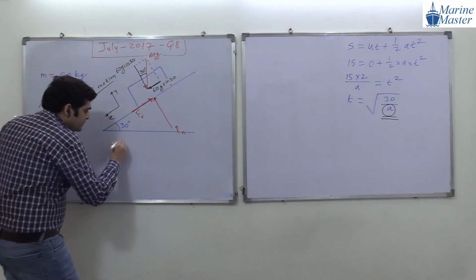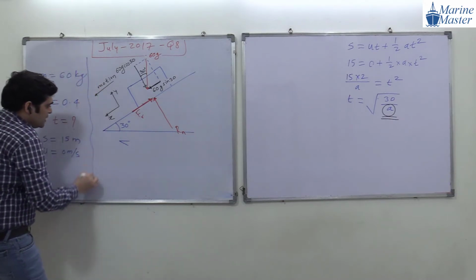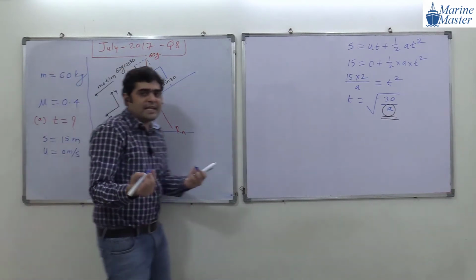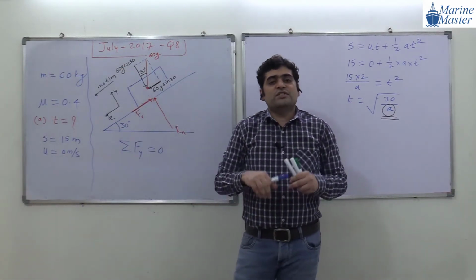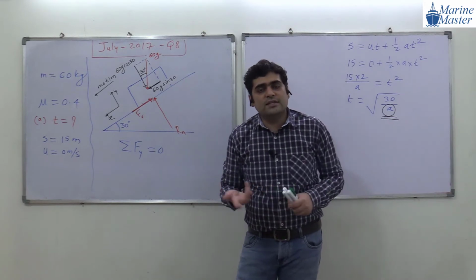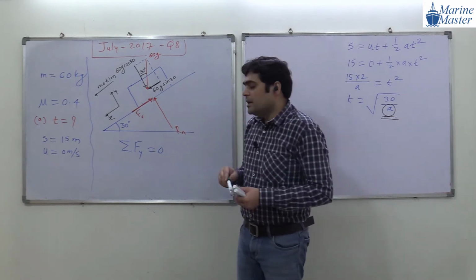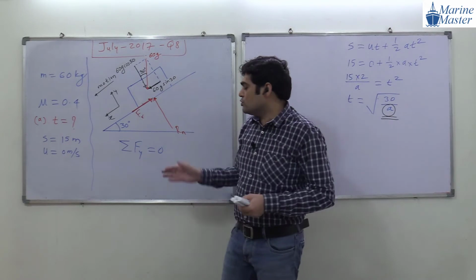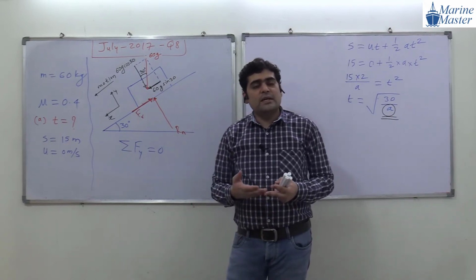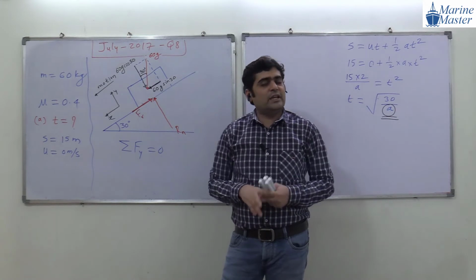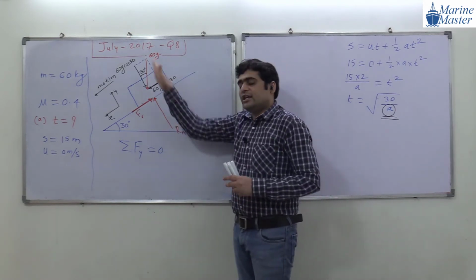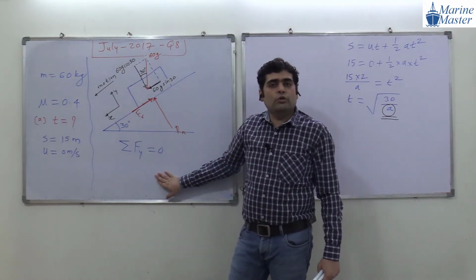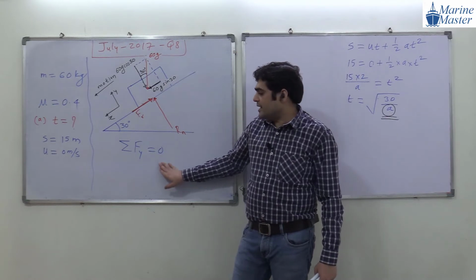So can I write down here summation of forces in y direction equal to 0? Because as there is no motion in y direction, it means the summation of forces in y direction will be equal to 0. Basically it will be MAy, but as there is no motion in y direction, we can write it directly equal to 0, because no motion means no acceleration, and acceleration will be 0. So in y direction the situation is an equilibrium situation. Okay guys, anyone have any doubt in this discussion?